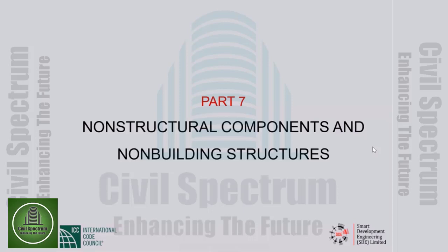Anyway, what I'm trying to tell you, it should not make any difference unless you have a distinctly unsymmetrical building. Gravity loads are not going to contribute significantly to the lateral deflections. So what load combinations is not irrelevant, but it's kind of a non-issue.